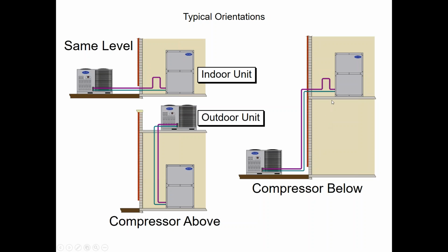Same thing. Residential equipment is the only time you're going to see a trap. With residential equipment, you'll never have a trap when the condensing unit is above. There's no reason for traps. We don't need speed risers, and we don't need double suction risers in residential equipment up through 5 ton.